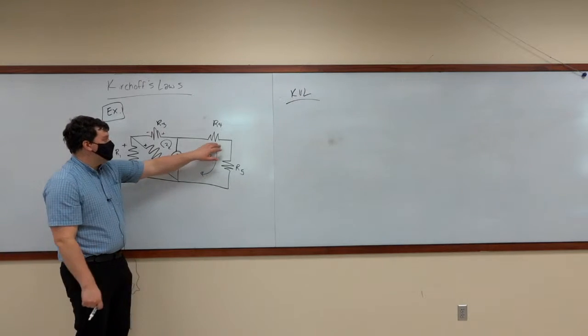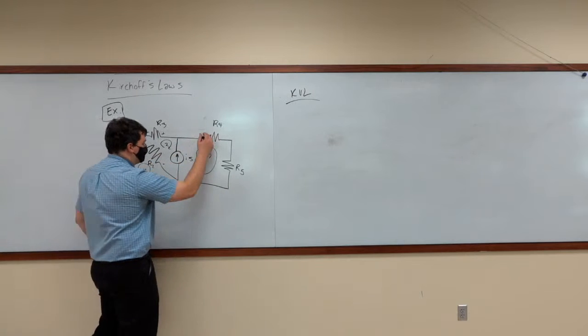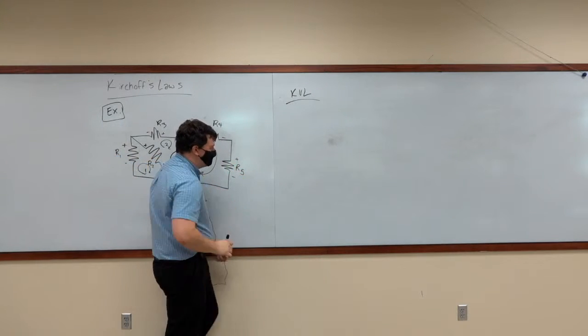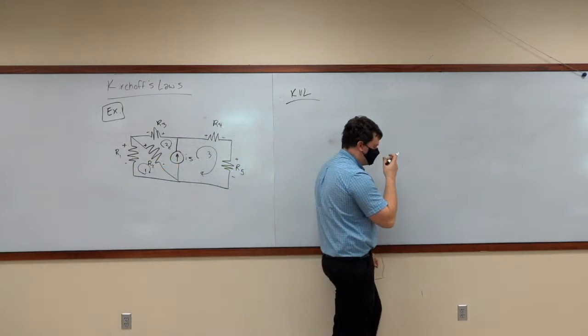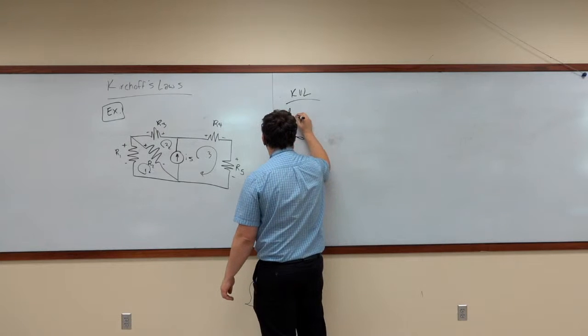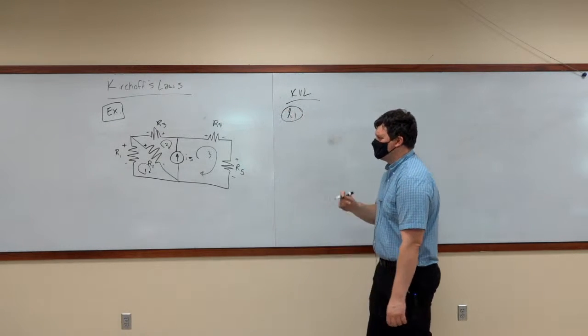All right, what about R4? Left or right positive? Okay, what about R5, top or bottom? All right, so we'll take those sign conventions and we'll go ahead and build our 3 loop equations. Okay, so we got loop 1 inside of pane 1. What components touch loop 1?